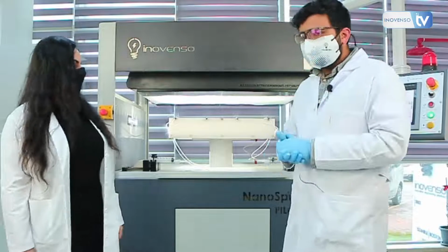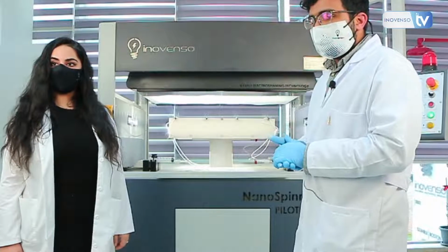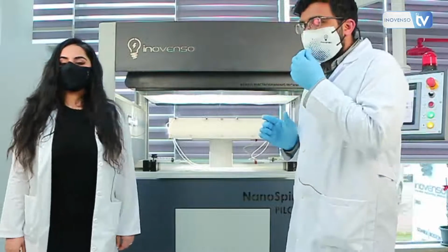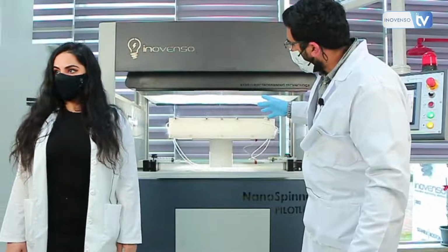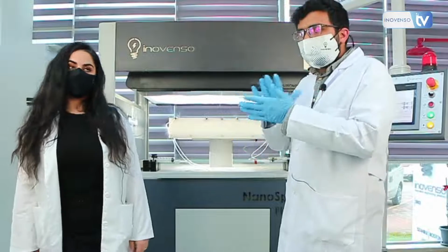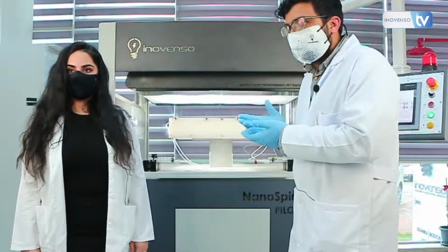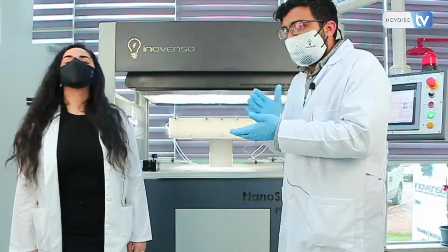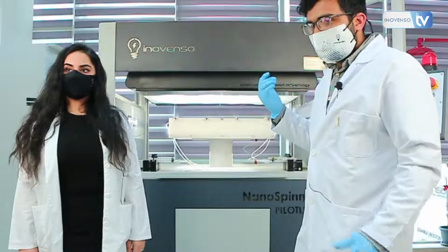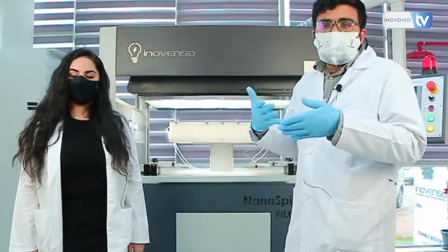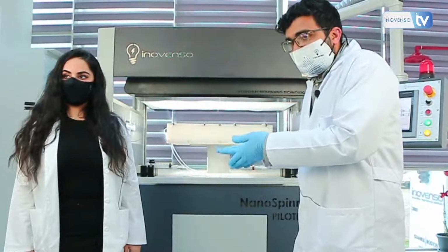Another important thing I should mention is that certain substrates need to be post-treated, or they need to be a special variant. For example, they need to be anti-static, because when you're introducing a high electric field, some areas of the substrate material get charged, and this causes an unequal distribution. It repels some of the charged solution. So it's best to use anti-static versions. For example, we've used polypropylene in the past, and in some areas it would get ionized. It would get electrostatically charged because of its nature. But now we use anti-static polypropylene to prevent that from happening. It should not hold static electricity, essentially.